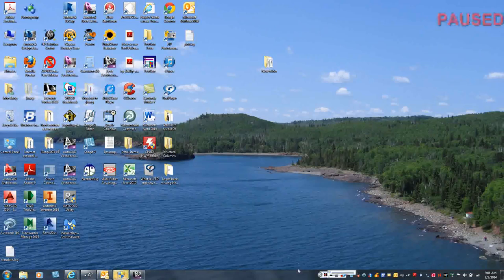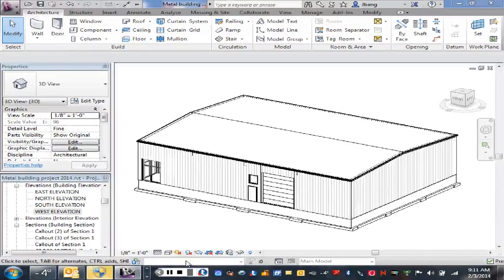So today let's talk about putting in downspouts on the project. What are some options as to how we can create that? We could create it as a profile and then extrude it, or we could create it as a sweep and have it put on that way. So we're going to talk about putting it on as a sweep.